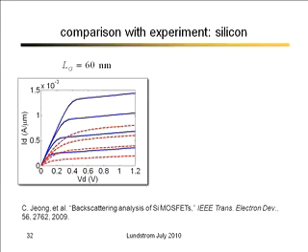So here's some data. This is the transistor we've been talking about. It had a drawn channel length of 100 nanometers, a physical channel length of 60 nanometers. The dashed red lines are the measured characteristics. And this is some work that my student Chang-Wook Jeong, who's sitting in the back row, did a few years ago. What he's showing there is he's superimposing a simple ballistic model for the same device with the same voltages, the same oxide thickness, onto the measured characteristics.